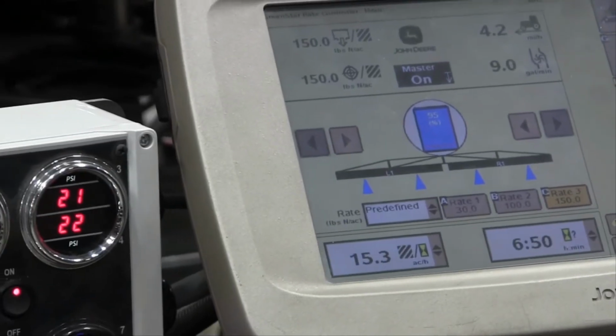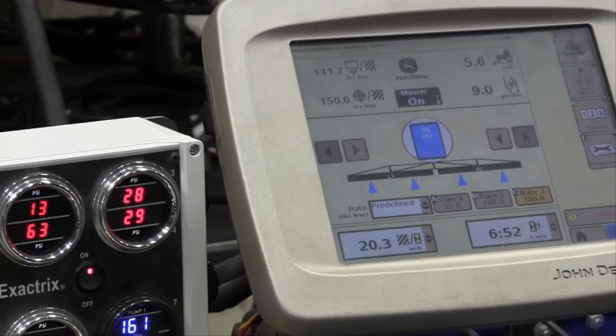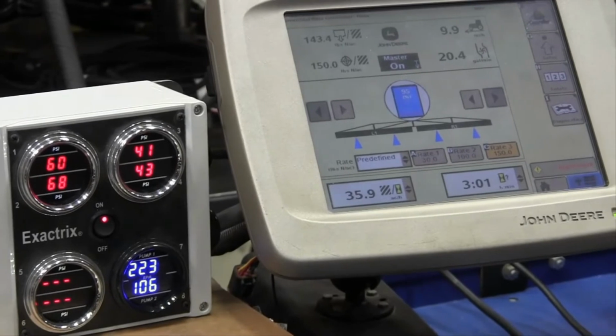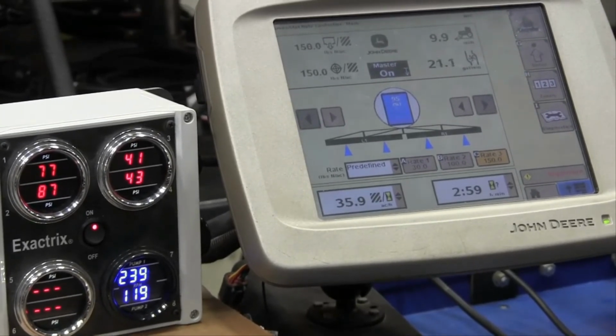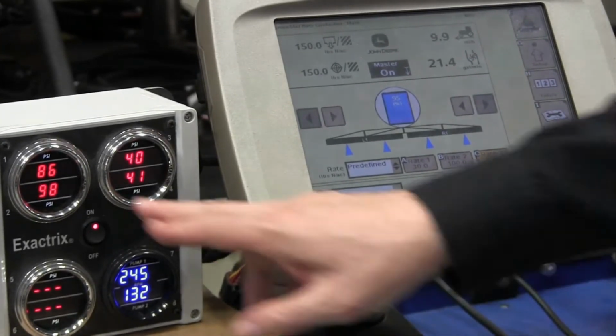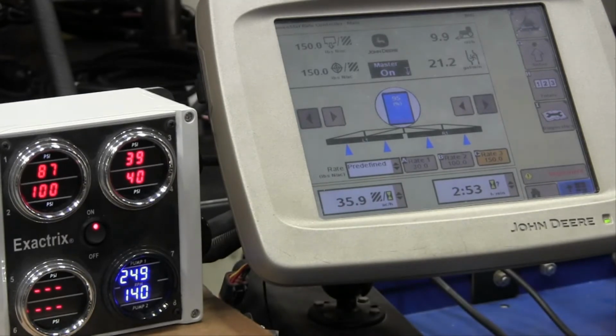Let me do this again. I'm going to turn it up to about 10. Comes up pretty nice, locks in a couple, 3 seconds. You notice the pressure came right up, and the pressure really tells the story. So even though the electronics aren't adjusting in the controller real fast, watch the pressure as we drop down to 4 mile an hour. There it goes. And the pressure came right down, and of course the controller's still trying to lock in. We're at 3.9 mile an hour.